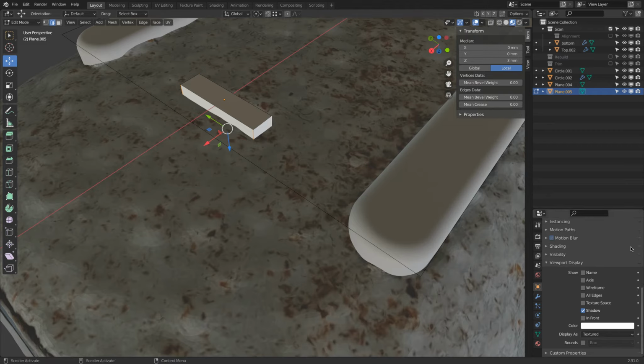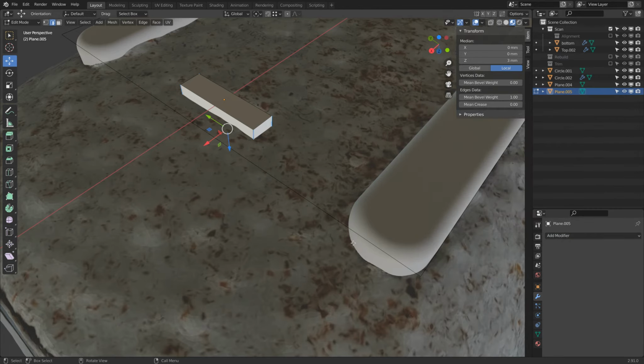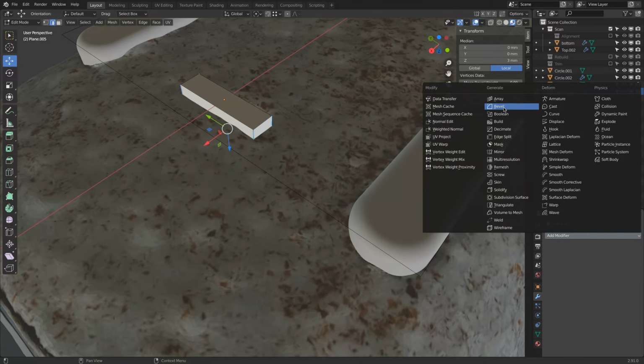Here we will simply bevel actually these edges, just to show you an alternative to it. The advantage of modeling everything rounded is this is perfect. Here, when I bevel these two edges, I have to be very careful where the bevels hit each other. So I have to trick a little bit. But the advantage of this process is later I can scale the whole object and I always maintain the same rounding at the ends. So you will see.